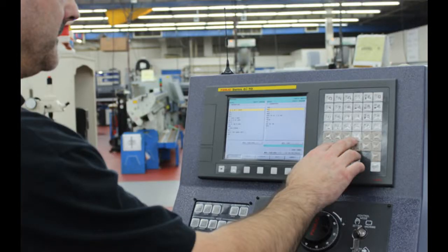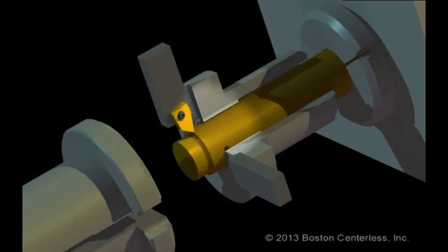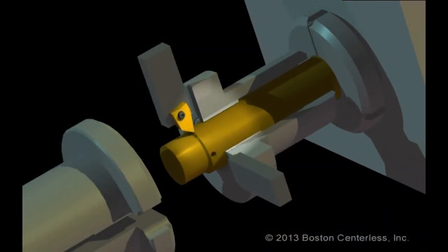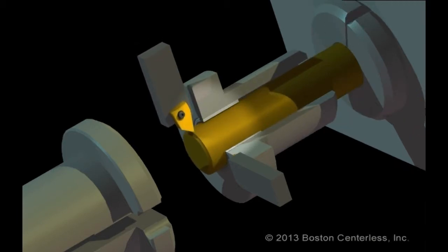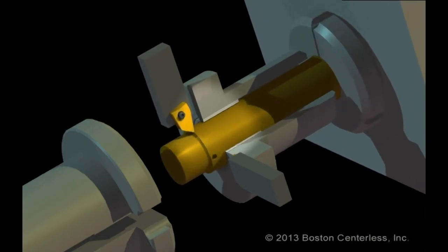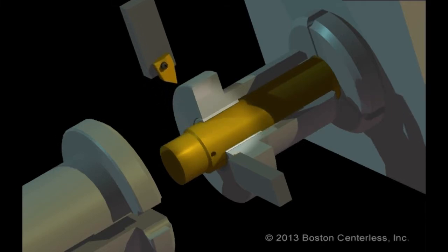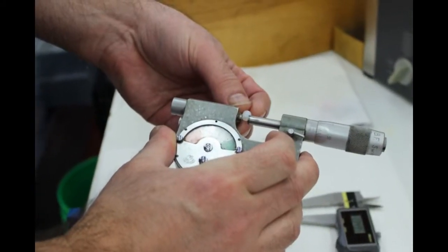First, let's assume you've set up the machine and you begin to ramp up your material speeds. As the bar RPMs increase, so does the vibration frequency, which is set up by the out-of-straight bar. At some point, depending on the material speeds and the actual machine configuration, the vibration frequency matches the machine's natural frequency and the machine starts to shimmy. Unfortunately, it's not as easy to detect as that of a steering wheel. It typically shows itself in out-of-spec parts.